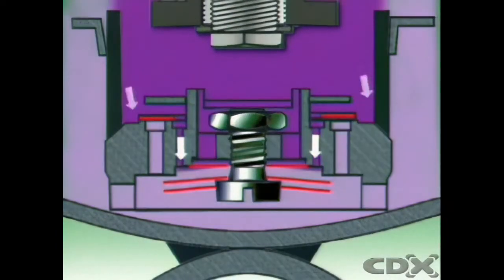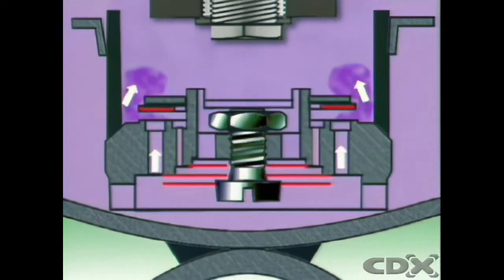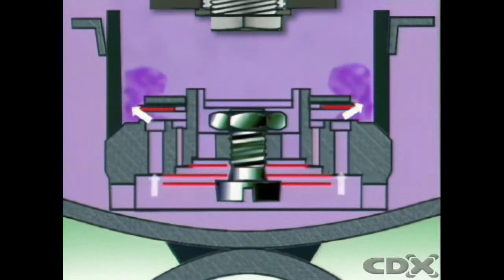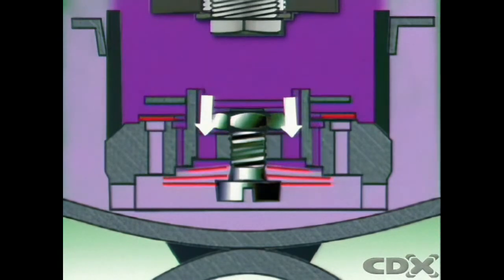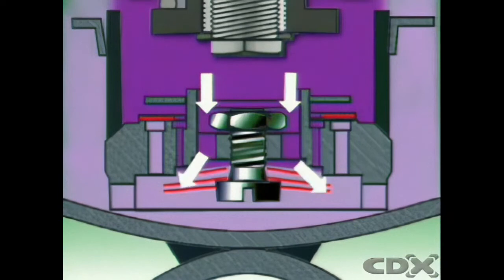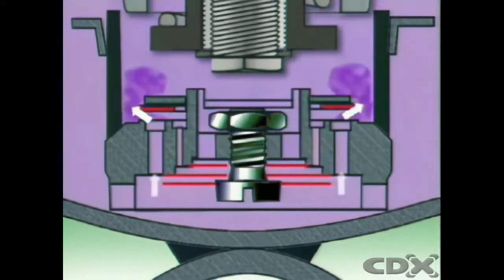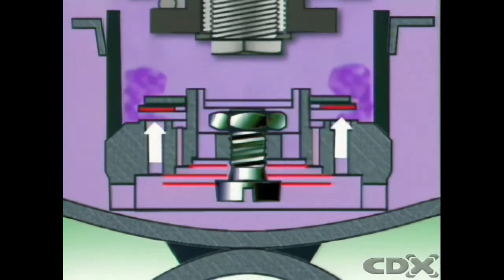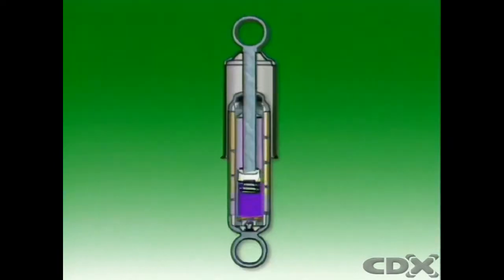The valves provide control over the amount of force required to pass fluid through them at any given piston velocity. They can be made to open in stages, according to fluid pressure. This allows light resistance to motion when the piston moves slowly, and heavy resistance when piston velocity is high.